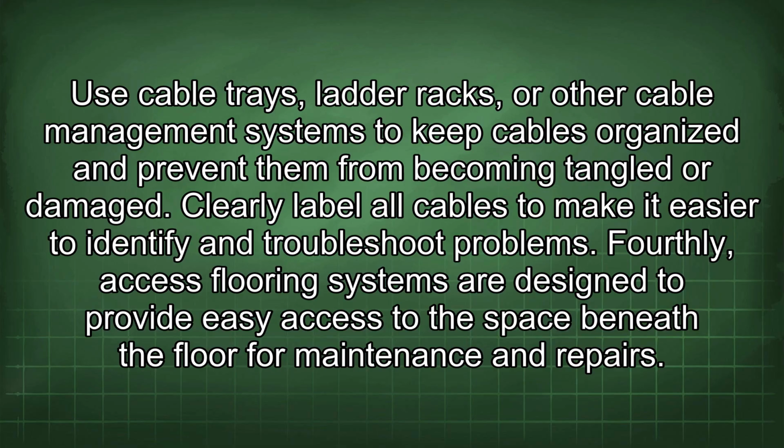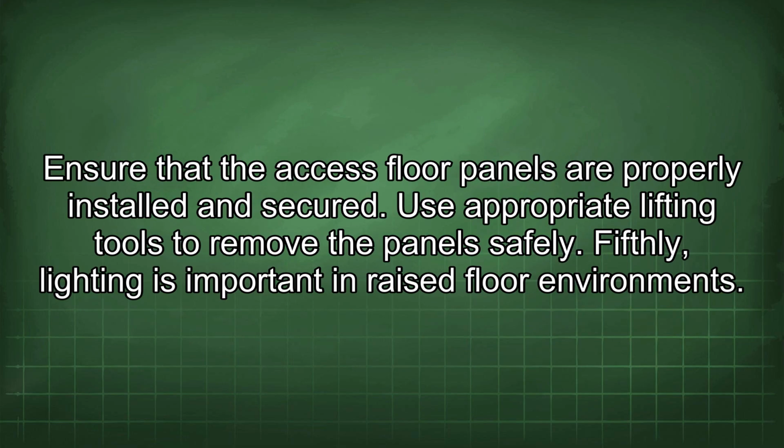Fourthly, access flooring systems are designed to provide easy access to the space beneath the floor for maintenance and repairs. Ensure that the access floor panels are properly installed and secured. Use appropriate lifting tools to remove the panels safely.